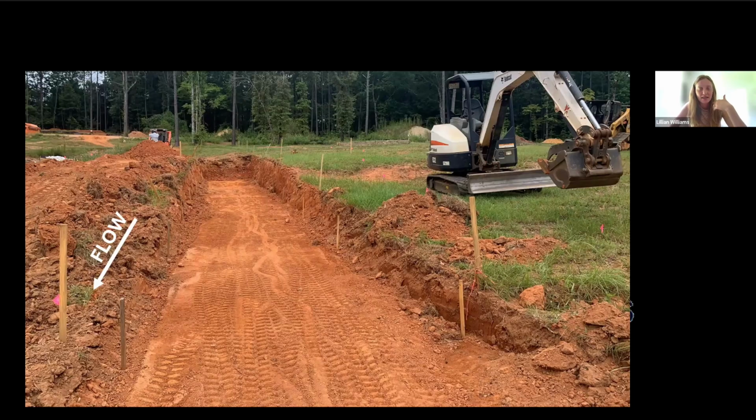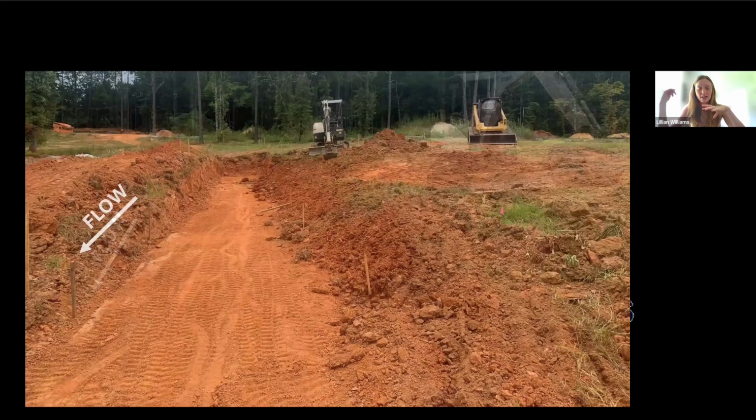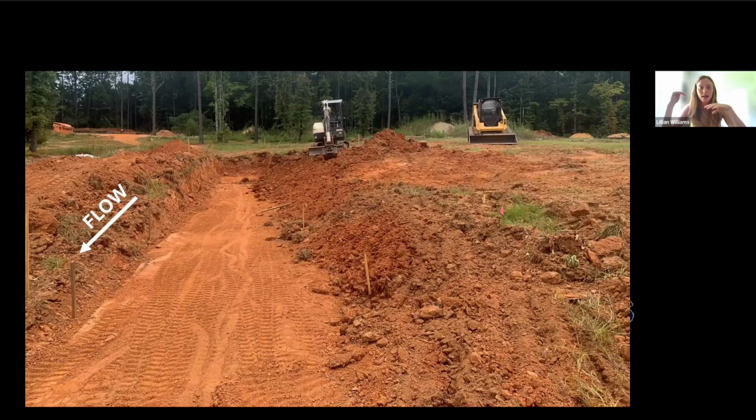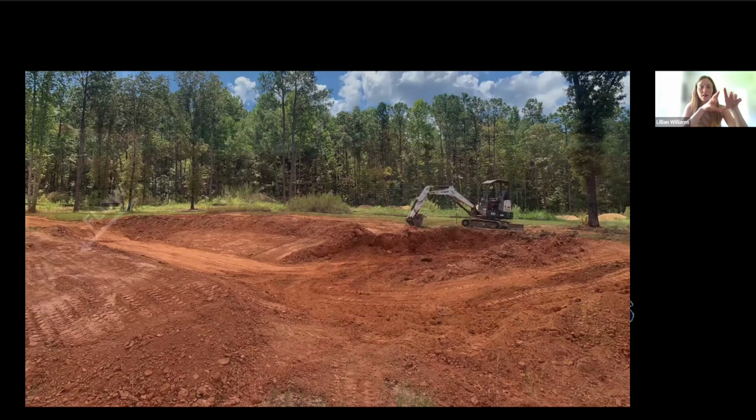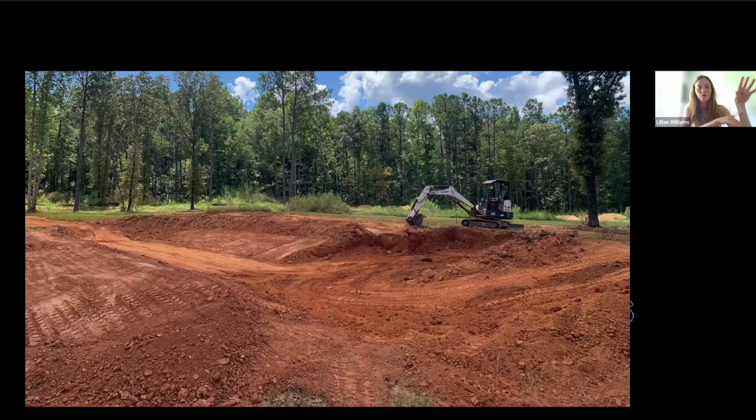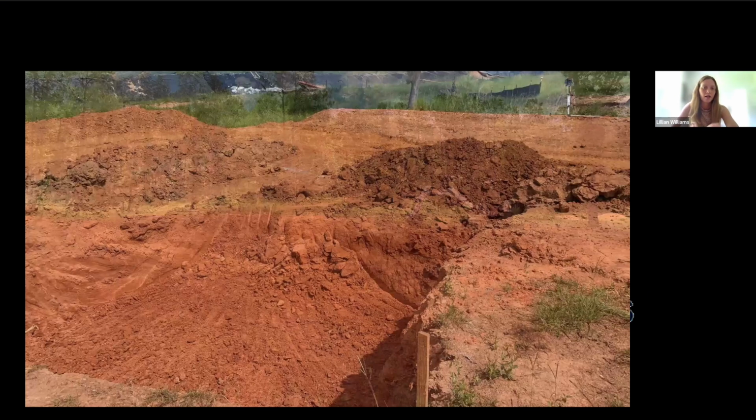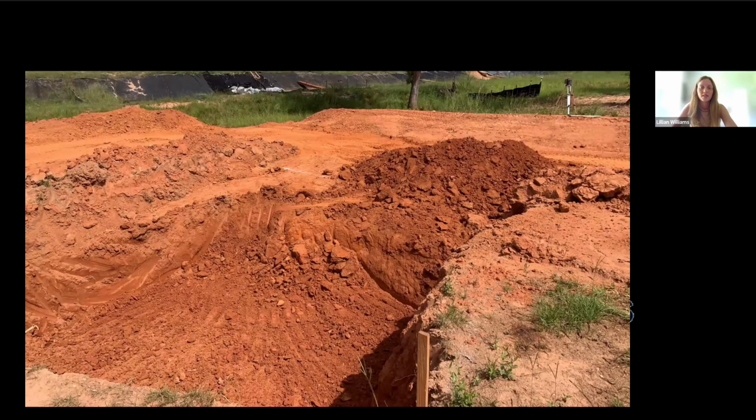But the flow is kind of coming at you, and you can see how we're cutting out this channel. And then we took back the side slopes to be able to get that from the plans that I had shown earlier. And then we continued and kind of finished that roadside channel on the left side of the screen and moved into that sediment trap basin, where we had to go pretty deep just because of the topography we were working with. So this is another angle of the basin itself.